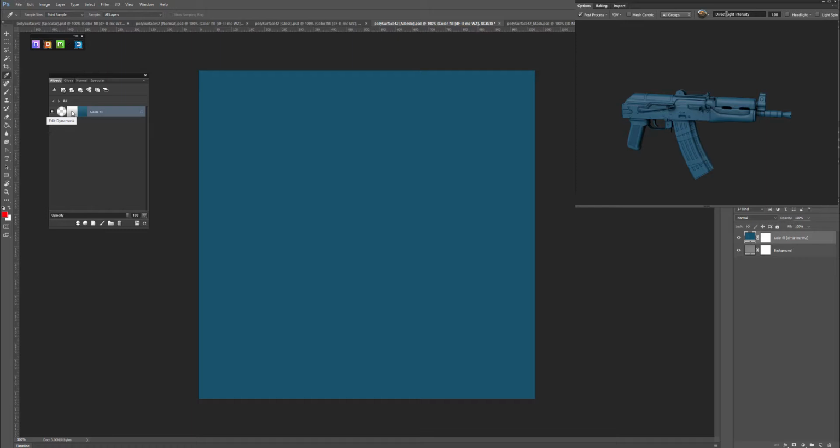So let's add a Dyna Mask. This is really editing your mask right here. Remember, if you watched the previous video, I went over masking and how that is primarily what DDO works with, and that's what I'm going to be using right now. So it's going to give me a little box here asking if I want to paint in full shaded mode, or if I choose no, in quick editing mode.